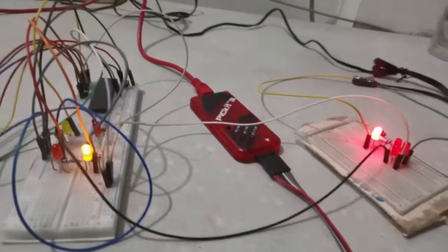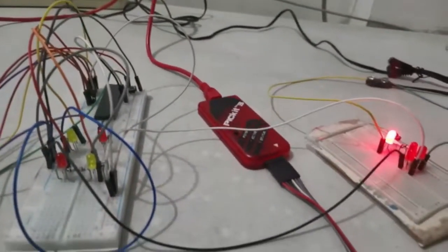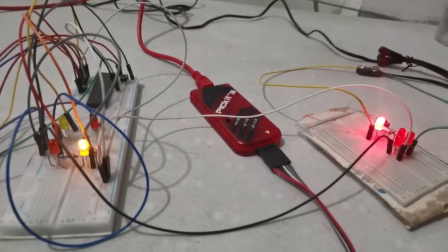Now let's move on to the other parts of our experiment regarding the interrupt. Using the interrupt, here we are, we have reset our code. So checking again our settings here in our pin module, we have SW1 as an input with negative IOC, with our system module here enabled, and our timer here where interrupt is enabled.